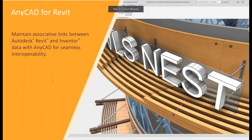All right, so as mentioned, AnyCAD for Revit: maintain associated links between AutoCAD, Revit, and Inventor data with AnyCAD for seamless interoperability. So again, if the customer or vendor made a change to their Revit file and you're utilizing that Revit file within your Inventor assembly design, you'll get that lightning bolt in the quick access toolbar. Click on that, and then that Revit file updates, and then you'll be able to model around those new updates.